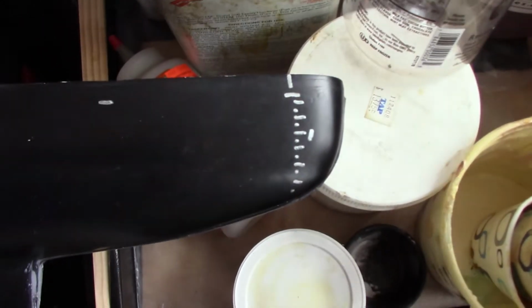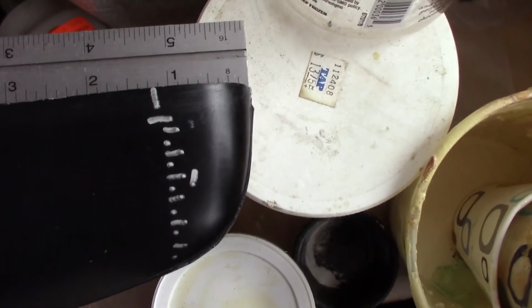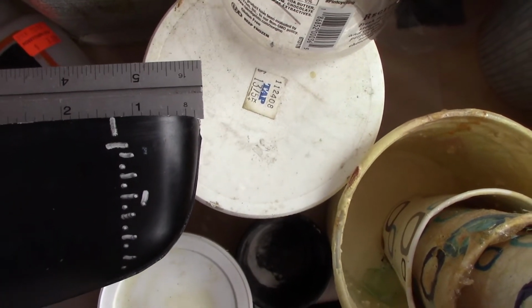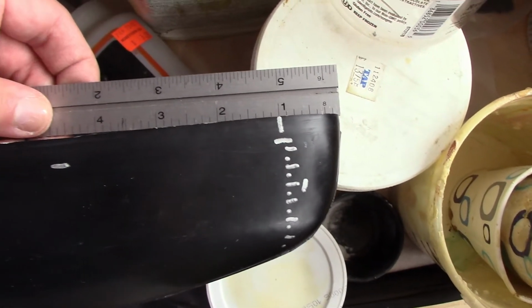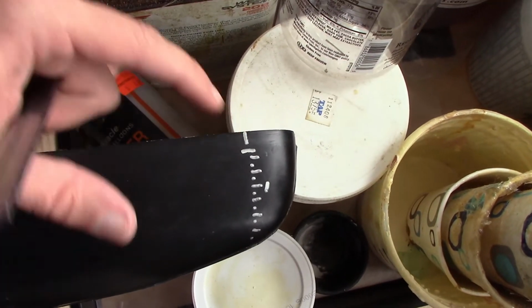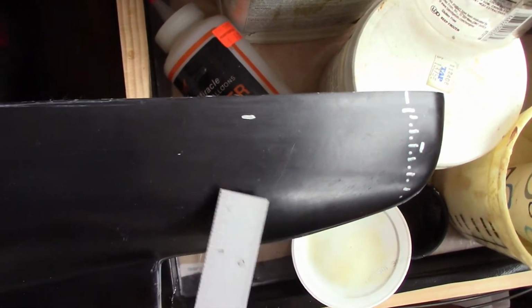So I already started with a few marks on the hull. Started at the stern here. The rule in the stern on the hard area is 1 inch from the furthest point back. So in this case, it's going to be at the top of the hull. Let me line the camera up so you can see that mark, this one right here. So that's going to be 1 inch, and it'll be a vertical line. And then along the top edge of the hull, I marked off the 3/8 at various points. So you can see that.